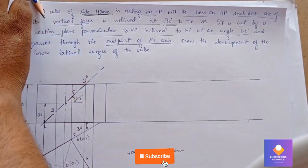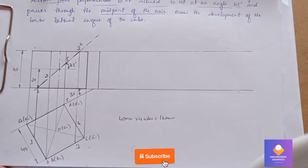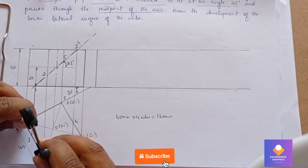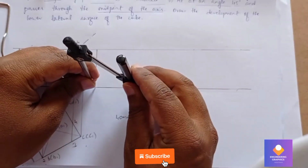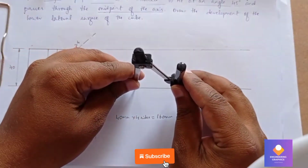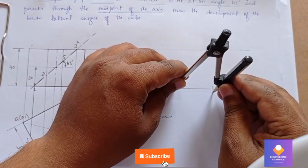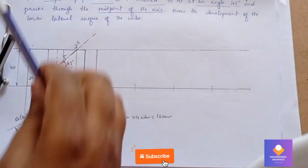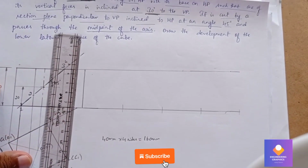Now we have to cut the arcs for 40 mm. 4 arcs we have to cut. You can see, the total length is 160, so 40 each, 4 arcs. 160 means 4 times you need to cut the arc. First arc, second arc, third arc, and fourth one. Now we have to draw the vertical lines where these arcs were cut.